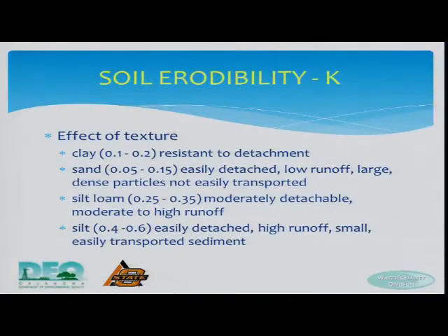Texture obviously makes a big difference, and Joe talked about this quite a bit. So your clay is a much smaller particle, and it's resistant to detachment. Your sand obviously is easily detached, but it doesn't move very far because it's bigger and it settles out. Your silt loam will detach moderately easily and has moderate to high movement in the runoff. So that has a higher erodibility factor. And then your silt has the highest erodibility factor because it's relatively small, it's easily transported in the runoff, and also easily detached.